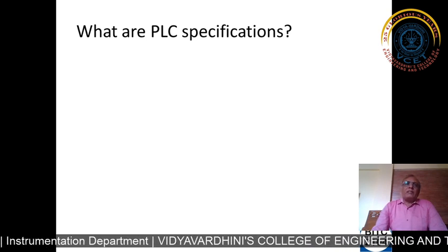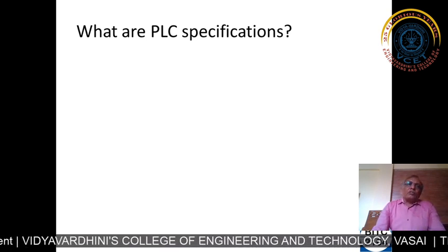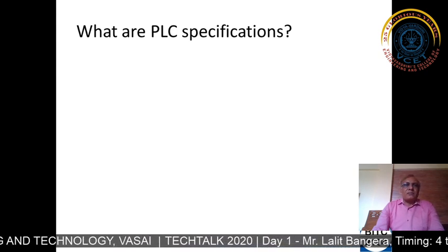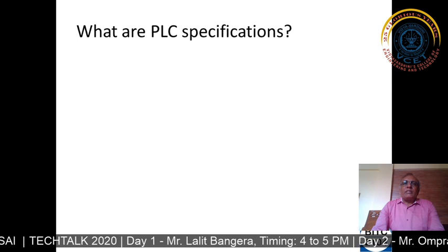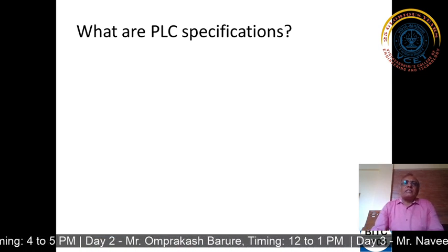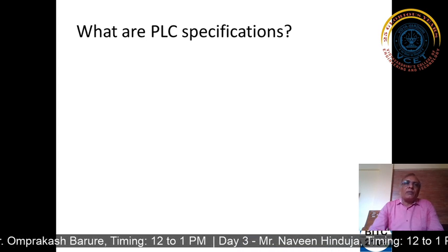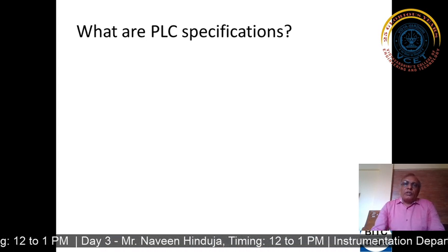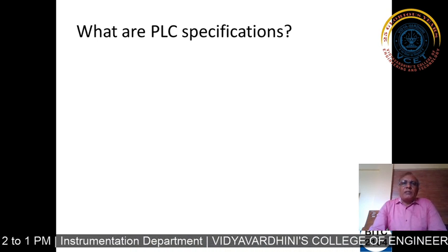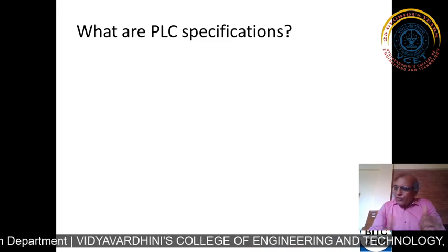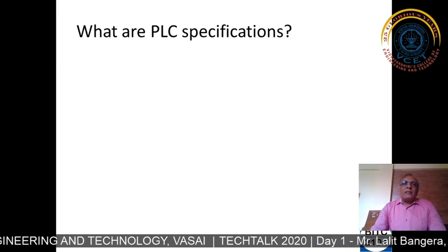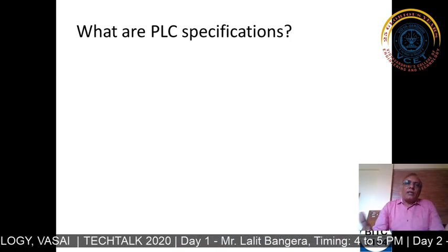What are PLC specifications? Be clear on those specifications, because we are technical people. Without specifications, we cannot understand any device. Talk about an orifice plate. What are the specifications of an orifice plate? You know everything about an orifice plate, but you don't know its specifications. That means you fail to understand a particular device. What should you know about an orifice plate? Don't you think you should know the MOC of the orifice plate? The thickness? The bore diameter and its position?